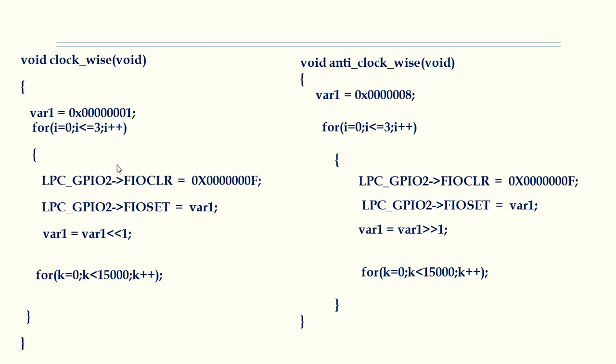Why? Because, if you recollect, with the arrangement the diodes are being connected to a value of 1, which means that you have to provide an inverse input from ABC such that the motor rotates. Effectively, if you look at the arrangement, the anode should be with the value of 1 and the cathode should be 0, but the internal arrangement is in the opposite direction. So by providing a value of 0 and 1, we make it rotate in the clockwise direction.